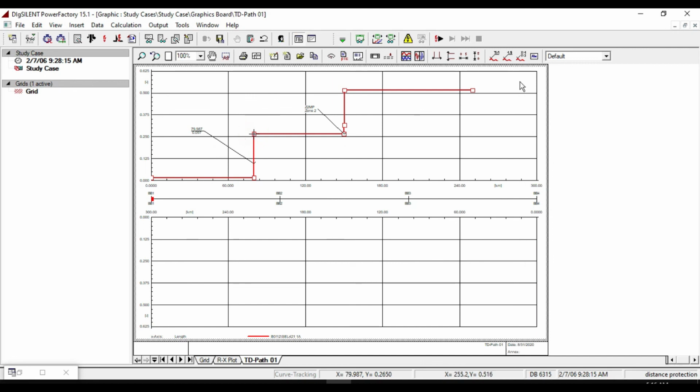For zone 2, we applied 0.3 second, and for zone 3, 0.5 second, as you can see here, but you cannot see the exact time value. That is because of a small time delay due to the contact relays that would be added to the time delay.